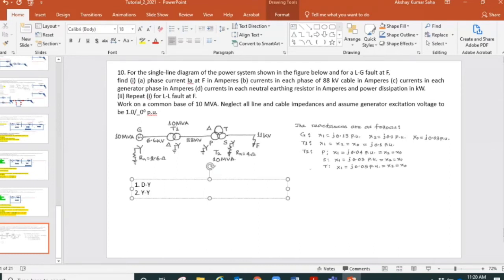Two transformers we have, and we want to connect them in parallel. Can we do that without thinking anything? We cannot. The reason is that when the voltage is transformed from the delta side to the star side, meaning stepped up or stepped down, it is not going to only step up or step down. The voltage will be changed by either plus 30 degrees or minus 30. I can't remember it now because it's not that straightforward, star or what. There is another level in that one.